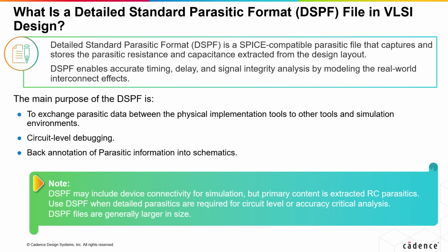Unlike simplified formats, DSPF includes device connectivity information, but the main content is RC parasitics, making it ideal for full circuit-level analysis where precision is essential. While DSPF offers unmatched accuracy, it comes with the trade-off of larger file sizes due to its detailed representation.